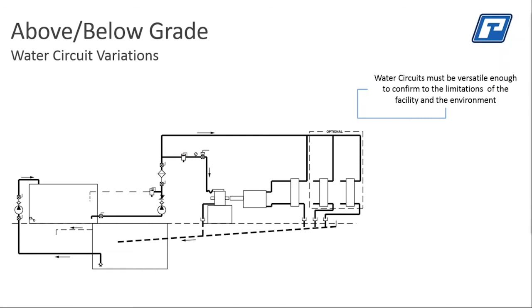The problem with these circuits is you can only run them the length of time that you have water for. So water flow rate is basically related to the load applied to the engine. Once the water gets up to a certain temperature, you're done. You can't run this any further.